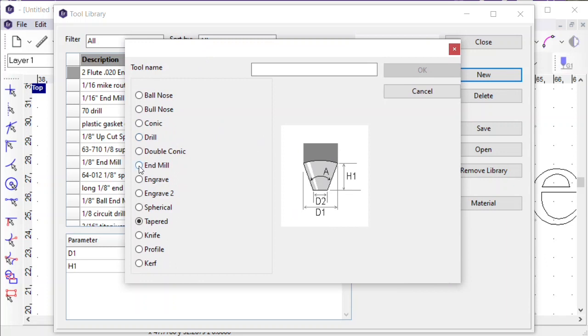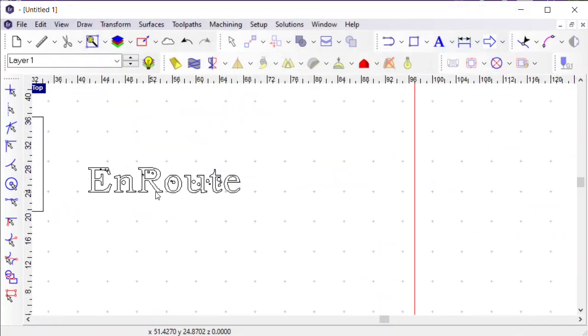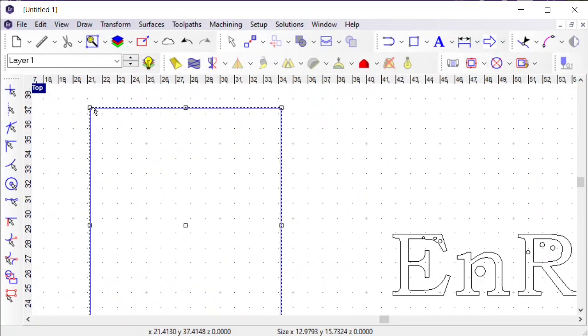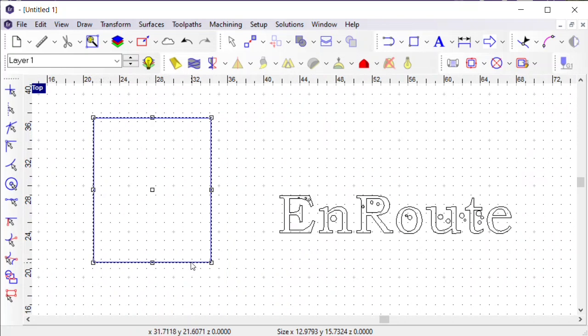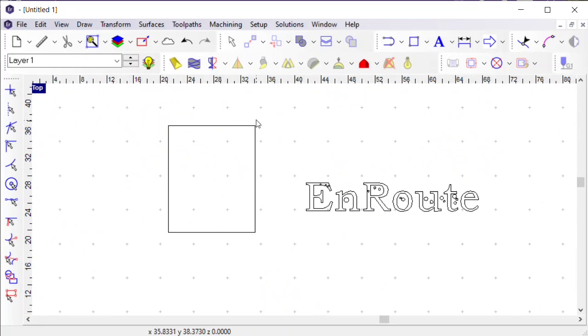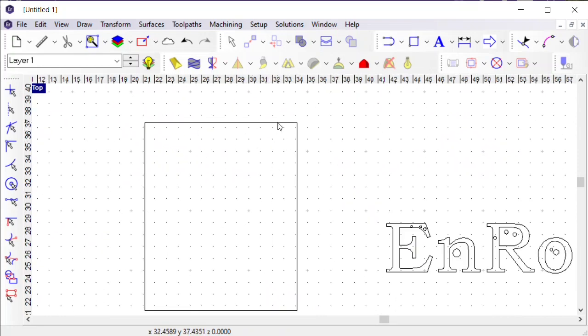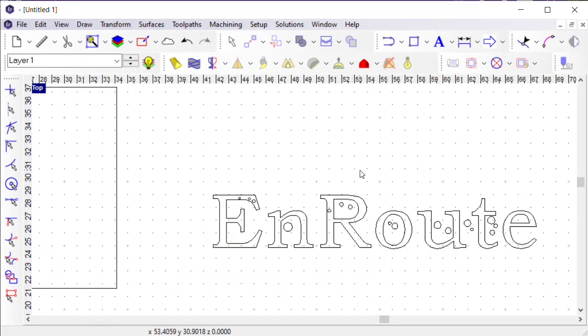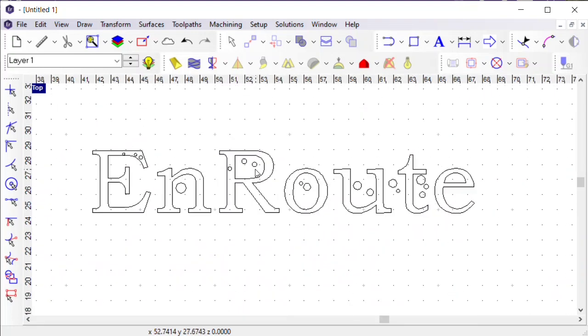And the big change is going to be, instead of just making an end mill, which is normally what we do when we have a fancy, advanced custom tool, we just make an end mill, we get the diameter right, and then in EnRoute, when you're looking at a toolpath, you're just going to see a general end mill toolpath. It's just going to be a square channel roughed through your material. So the benefit of having the profile in our software is we can actually now, when we do a rendering of the toolpath, or we see how the part is going to cut, we can see that profile in the edge of the material. So that's really, really a neat advancement in the software.